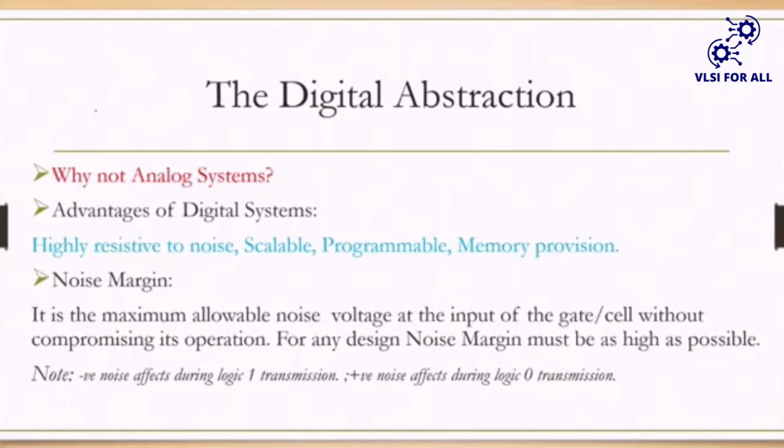If we give more than 5 volts, that IC gets damaged. Here only 4 elements are working with even 30 volts, but there is a big architecture with so many elements, and they work only with around 3 to 5 volts. That means, remember team, you cannot work at high voltages in digital. If you want to work at high voltages, then please go to analog systems.